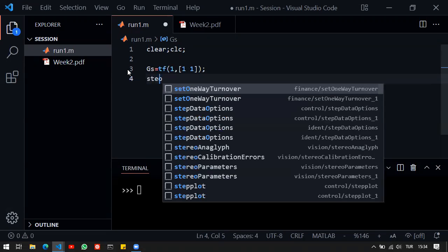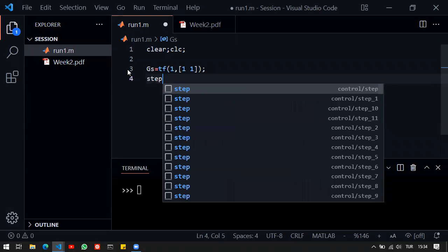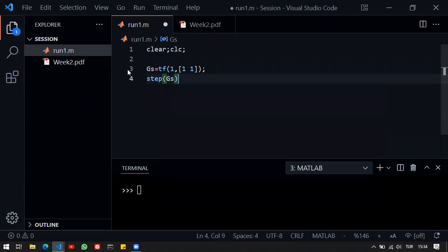For example, I know that if I call the step function on this transfer function, I will get, for example, 0 overshoot. Because it has a real pole, I can directly conclude that this will not have overshoot. And I can also tell that this will have 4 seconds, roughly, of transients. So the settling time would be 4 seconds.